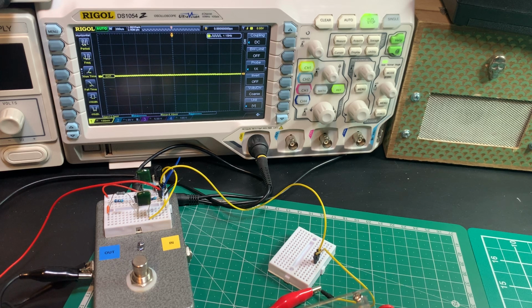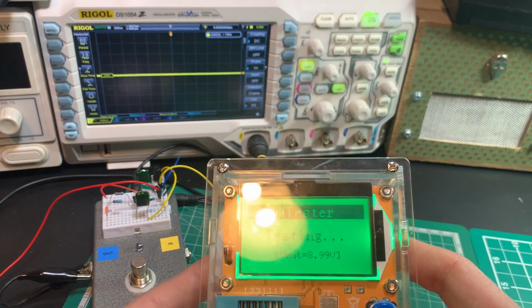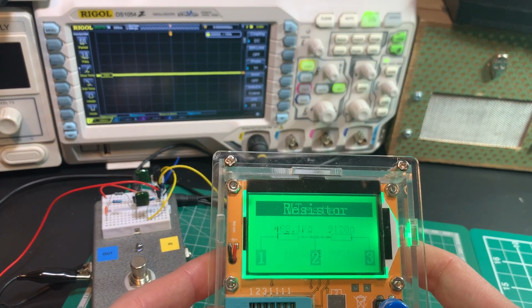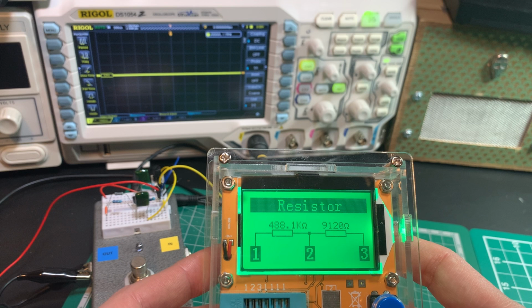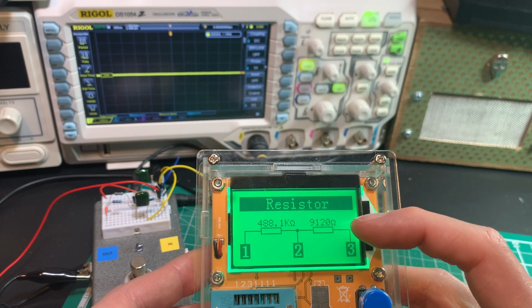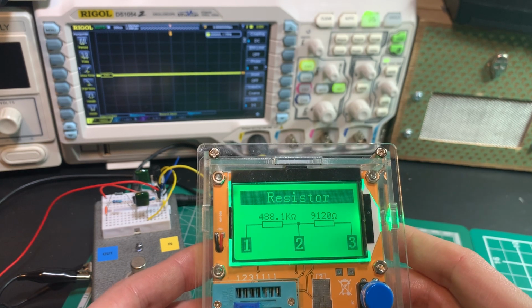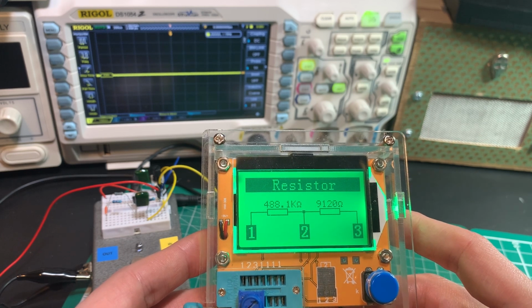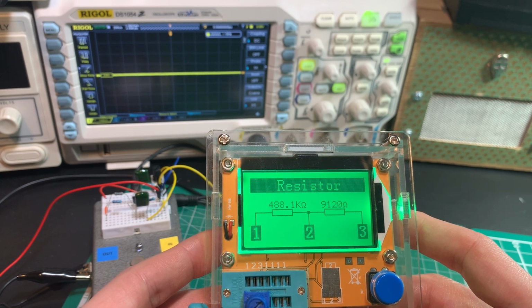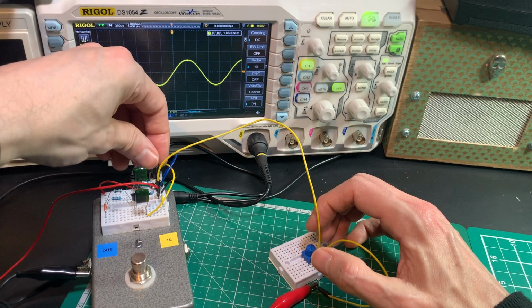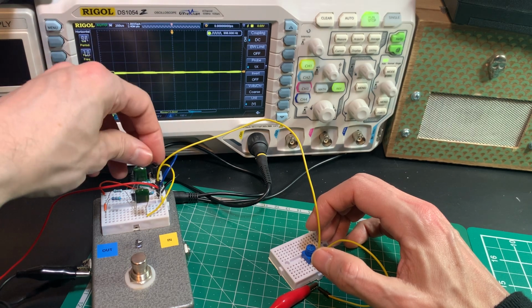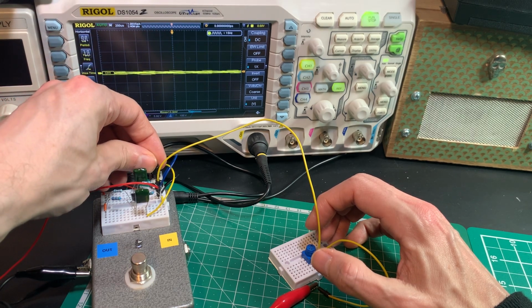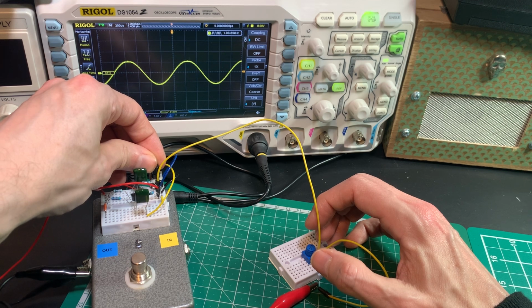So the volume's not attenuating any of our signal basically. So 9,120 ohms. That's what we calculated, 9k. Now let's move the output potentiometer slightly and try the same thing. Okay, so if I take this all the way down, I'm not going to get any signal. So I'm just going to back it up to where we're getting 200 millivolts.